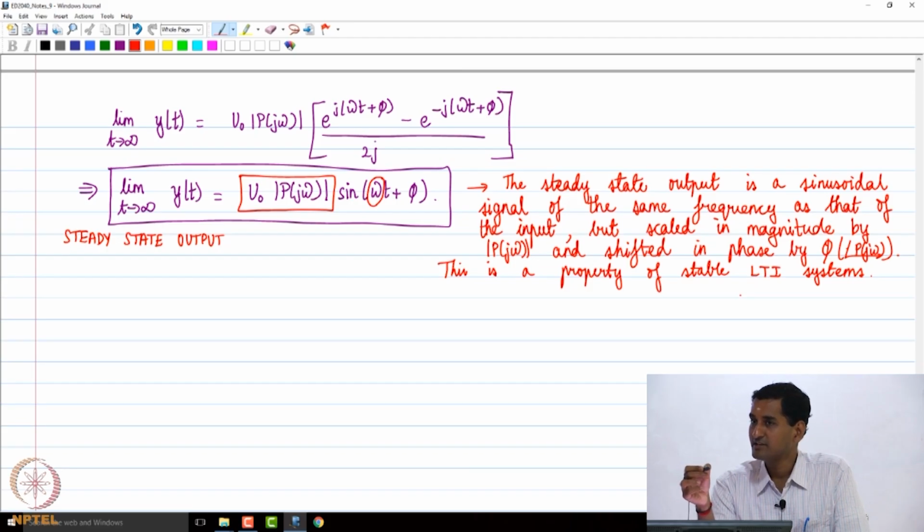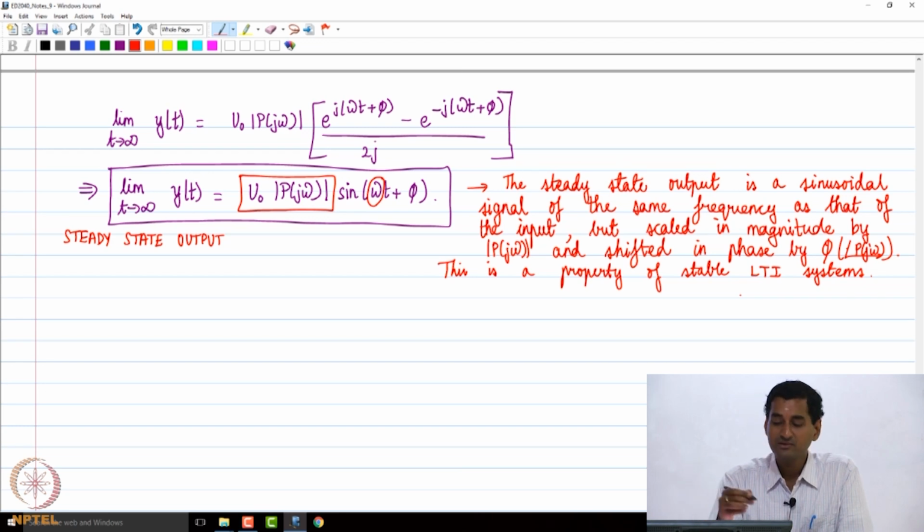We essentially wrote down equations of motion, governing equations in the form of linear ODEs with constant coefficients. Then we took the Laplace transform, applied zero initial conditions, and then calculated the transfer function. So, we will also figure out how to empirically determine that. There you will see that the step response and the frequency response are going to play a vital role.